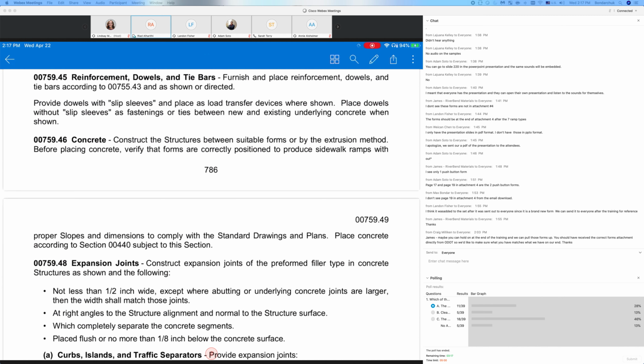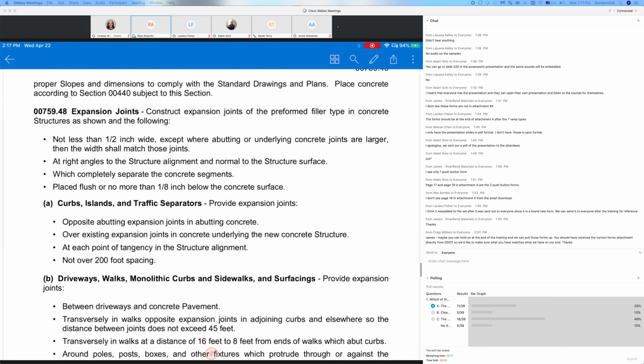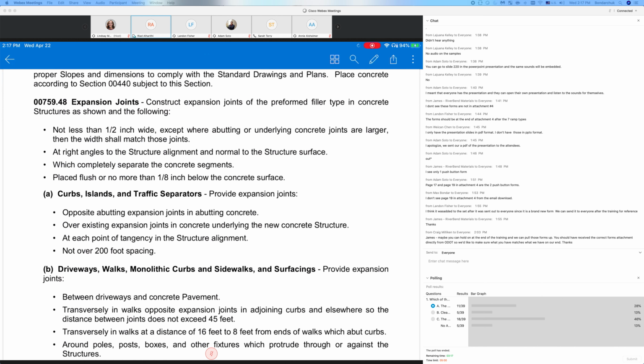You went in the field, you verified that you have the plans, you built them according to the plan, or you modified them, and the engineer gave you the okay to modify them. You prepared yourself to pour the form. You verified them the first day, but then on the day of the pouring it is very important to go back and verify them again, because that's one step before your last chance to get them done correctly.